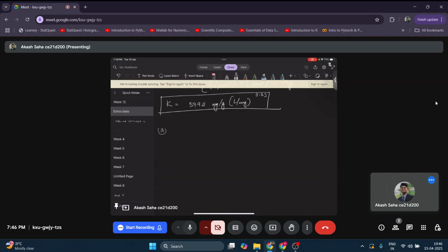So part A asks what is the effluent BOD concentration. That is nothing but S is equal to Ks times (1 plus Kd theta C) divided by (theta C times (Yk minus Kd) minus 1). So very simple. Then we will put all the values.